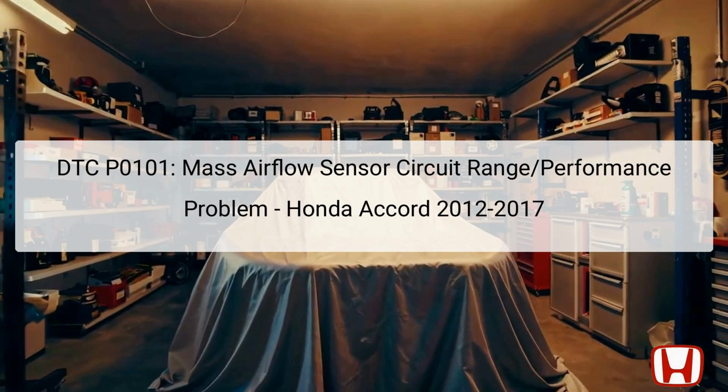If the PCM detects a significant difference between the actual airflow measured by the MAF sensor and the presumed airflow, calculated from readings of the manifold absolute pressure, MAP, sensor, it triggers this error code. The MAF sensor is typically located in the intake air duct just before the throttle body, ensuring accurate measurement of the incoming air. The PCM monitors these values during normal engine operation, and any discrepancies can lead to engine performance issues, including decreased fuel efficiency and increased emissions.